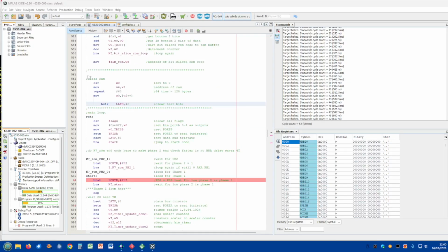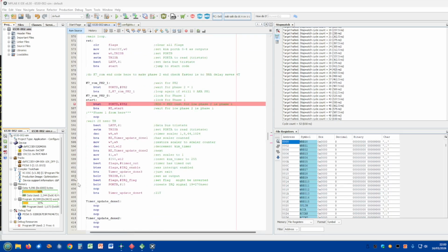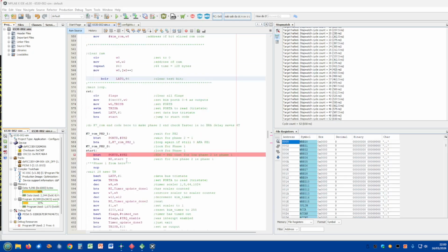And then we get to this point here, the very last bit before we actually start running the program, where I clear it. And then we come into the main sequence just here. And we start running the code, which always loops back here, backwards and forwards through here. Now the only way that port G pin 6 would ever get turned on is if the processor resets.